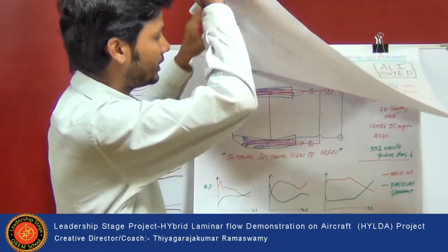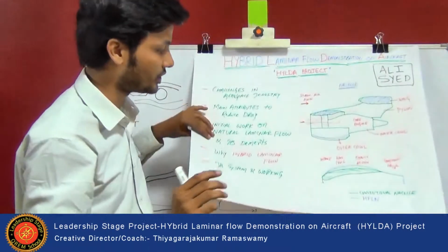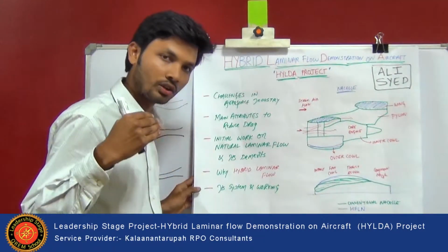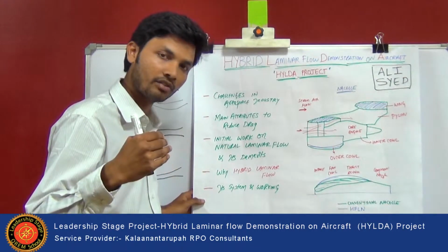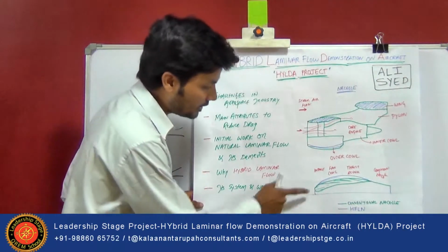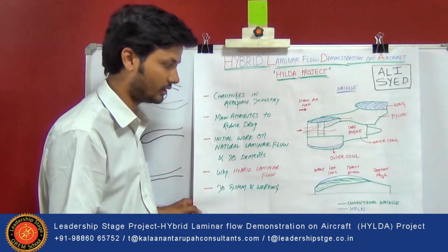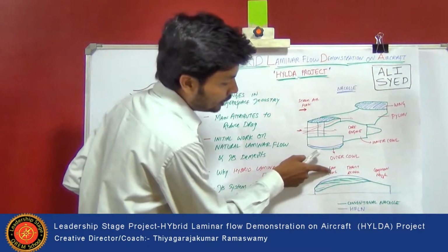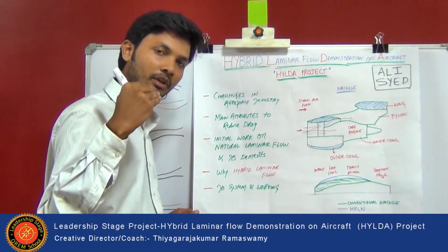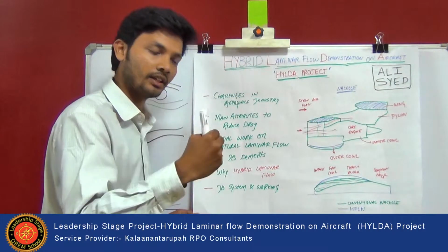On the CFM 56 5C engine, here you can see what changes in the design are coming. The maximum diameter of the nozzle will increase because of that. Here in the green, what you can see is the actual nozzle design of the CFM 56 5C engine. The blue end which you see on the top, the maximum diameter, is increasing.